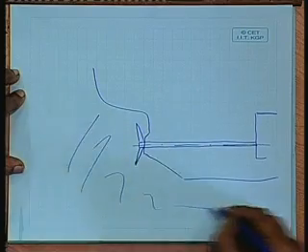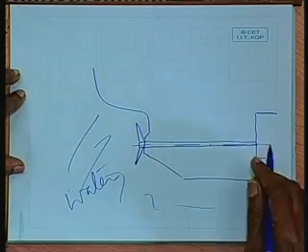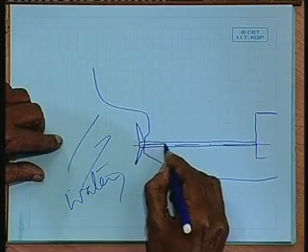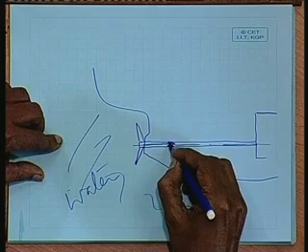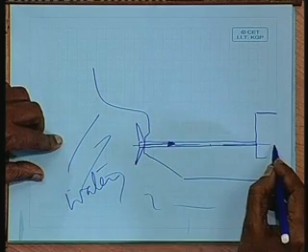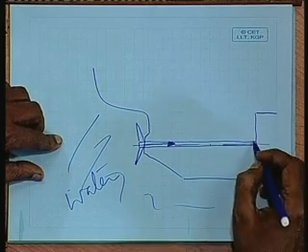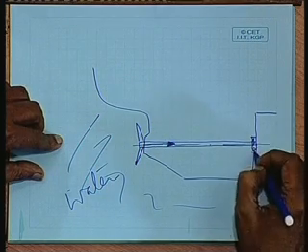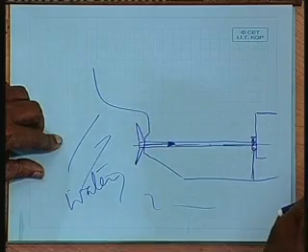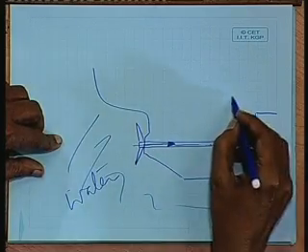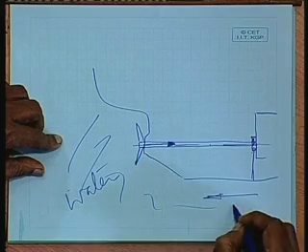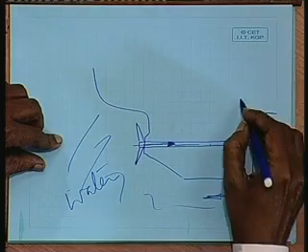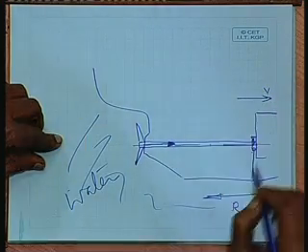This medium is fluid, water, and produces a thrust or an axial force in this direction, which is finally transmitted to the ship along the propeller shaft. And since the propeller shaft houses a bearing here, thrust bearing, through the thrust bearing it is transmitted to the ship structure, and the force is applied to the ship, and the ship moves forward, overcoming this force R, resistance, which is experienced by the ship at a particular speed v.